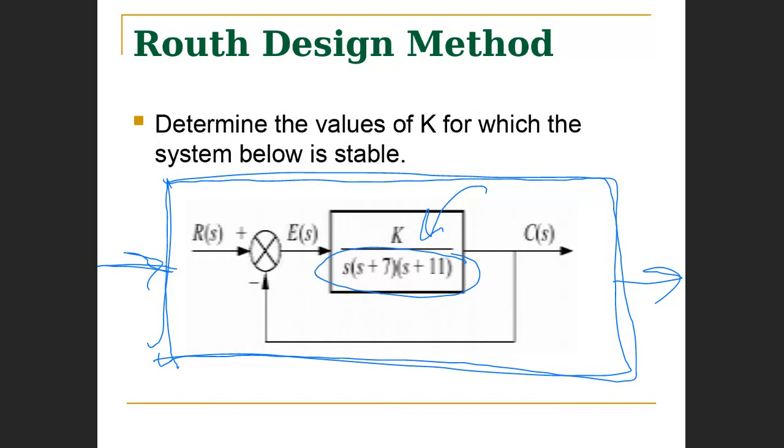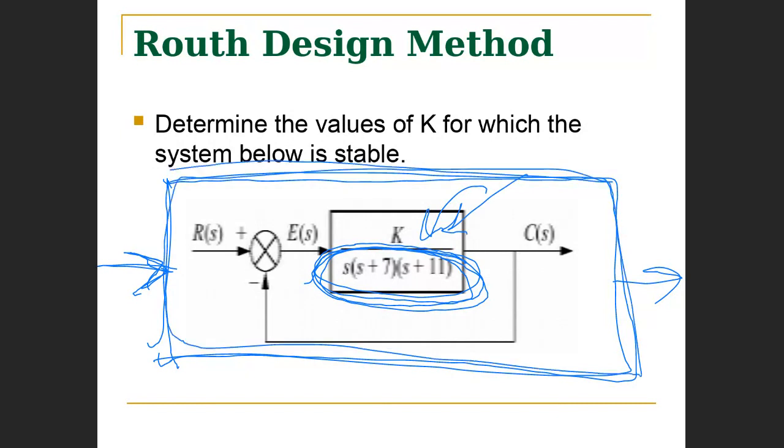You're supposed to know by now that it's not a little thing. You can simplify it, which means you use one block to represent everything that is inside here. Now, what I'm trying to get your attention on is that when you pick out this expression and call it the characteristic equation, it is not true, because this expression here in the block is not what describes this bigger block. Are you able to see that?